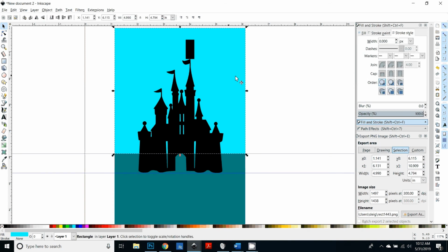Eventually I'm going to union these together, so what I want to do right now is click this one. I'm going to hold down Alt and click the down arrow. Holding down Alt makes the increment of the down arrow smaller. If I click the down arrow without holding it, it moves it quite a bit. You can see I'm clicking down and clicking up. If I hold down the Shift key and click down, it moves it a lot. If I hold down the Alt key and click down, it moves it just a tiny amount.